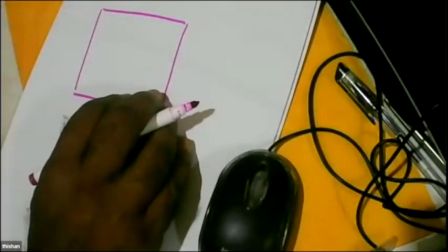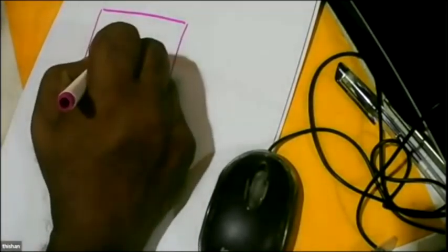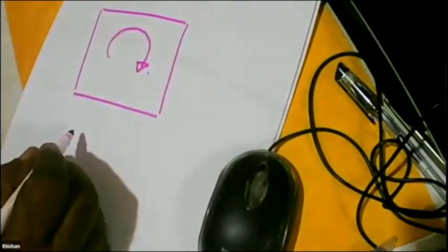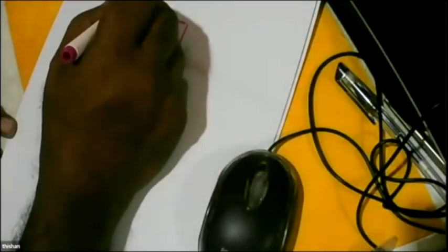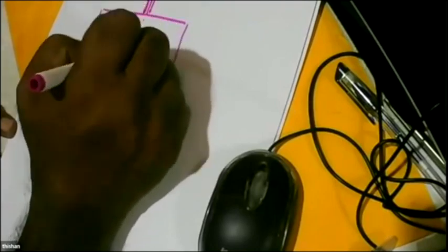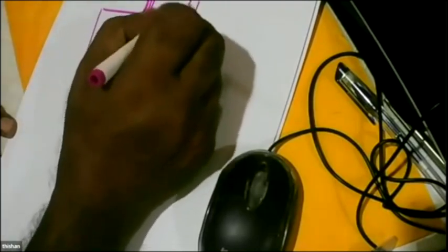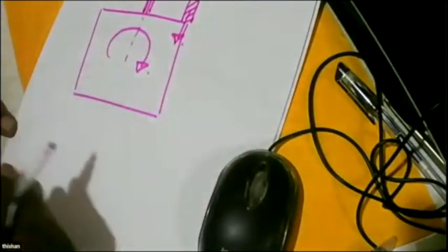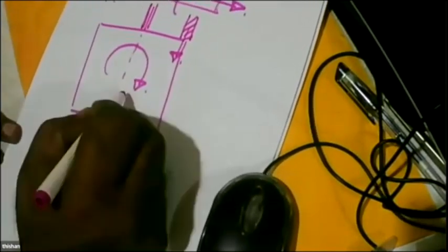And what is important is, when it is subject to torsional moments, it should be able to resist it. And the problem is, if you want, you can have the beam loaded with some walls on the center line like this, but some other walls might come here and transfer the loads here. So if the loads are transferred at a place like that, what could happen? We'll get torsion.